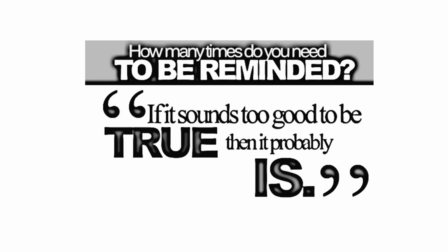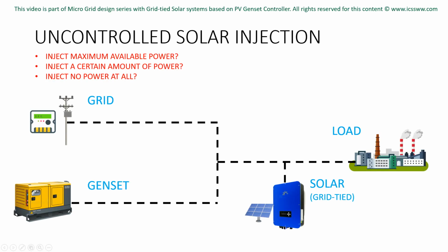There is just this problem that a grid-tied inverter is a bull and will do whatever it can with whatever primary source it is working with. As the inverter completes its grid/DC checks, it will start producing as much AC power from the available DC power and inject it into the power system. There are various scenarios where we would want our inverter to produce full power, a specific amount of power or no power at all. Here are some scenarios.